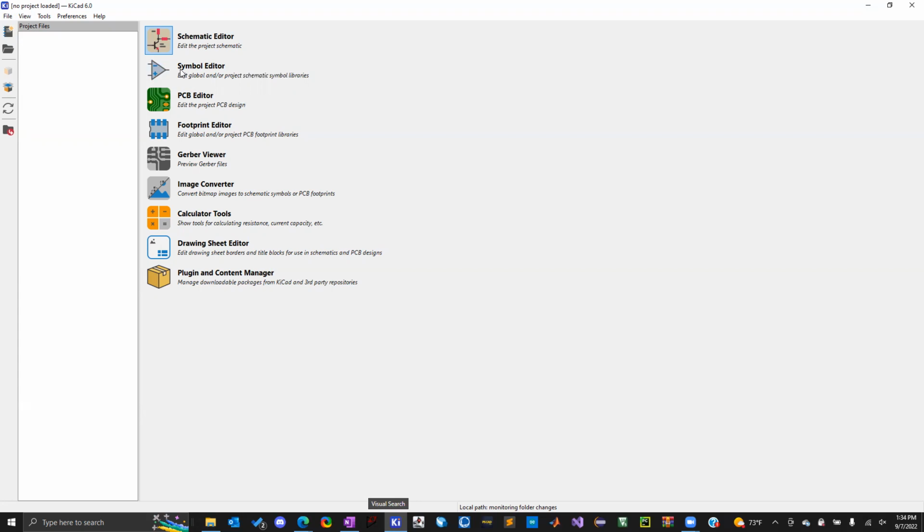So if it's a chip that usually uses a QFP package, which is kind of square shaped with a slice on one of the corners, you can make the symbol look just like that. And there are two methods for organizing the pins. You can either have all the input pins on the left and all the output pins on the right, or you can order the pins exactly how the chip will actually have it.